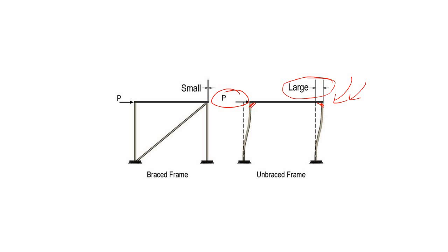In all of the sophisticated structures like pipe racks and others, you know that this lateral deformation or drift is not much allowable. So what is the solution to reduce this drift or lateral deformation? Simply you can put a bracing, or you can make all these connections pin connections and then put a bracing like this. Now if you provide any lateral load, it will be transferred like this, come to this joint, and finally through this bracing it will come to the foundation.